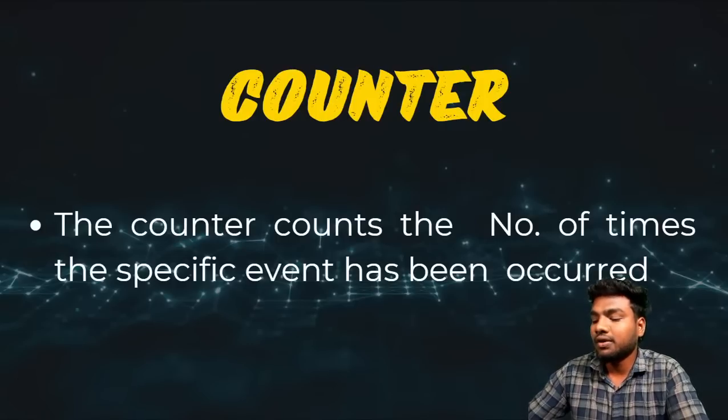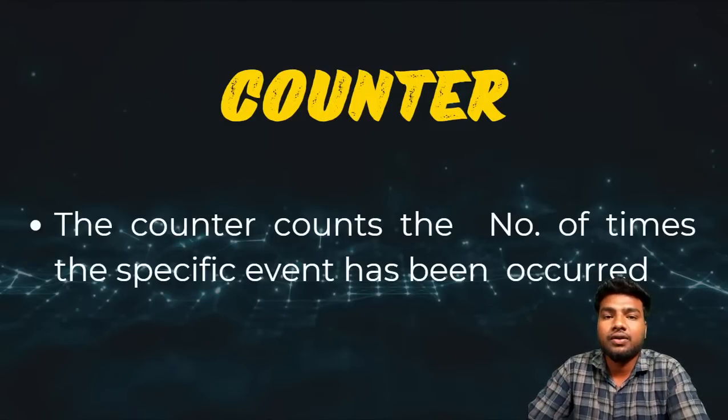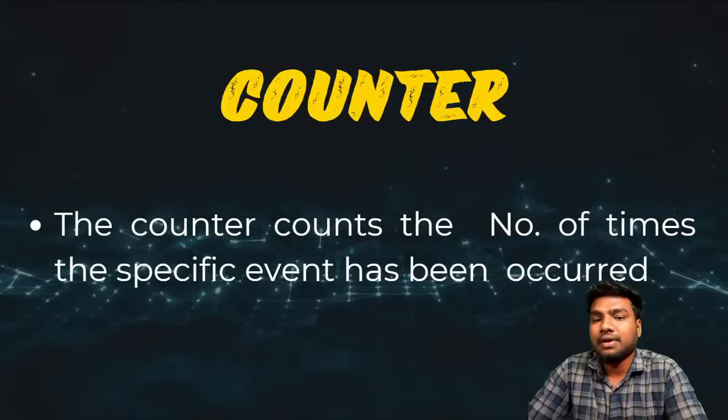Based on the counter, you can do frequency divider operations, like increasing or decreasing the clock frequency, like 50 megahertz to 20 or 50 megahertz to 100. By using a counter, we can achieve that. Let's see that kind of clock division in upcoming sessions, while implementing on FPGA, like LED blinking or seven segment display.